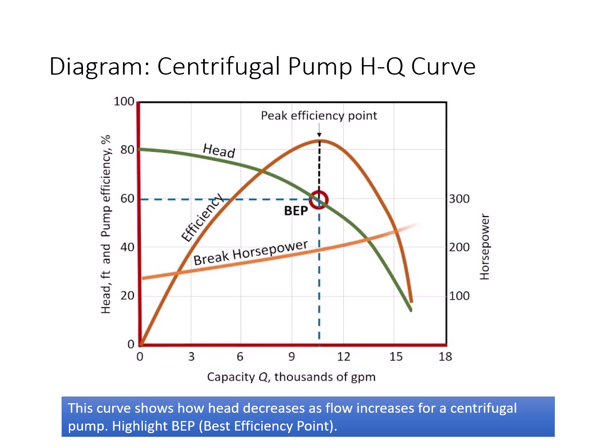So if your flow rate is in this range, maybe it is 9, 10, 10.5, your flow should be 10.5 to work at best efficiency, at peak efficiency. And of course the horsepower will increase by increasing the flow rate.